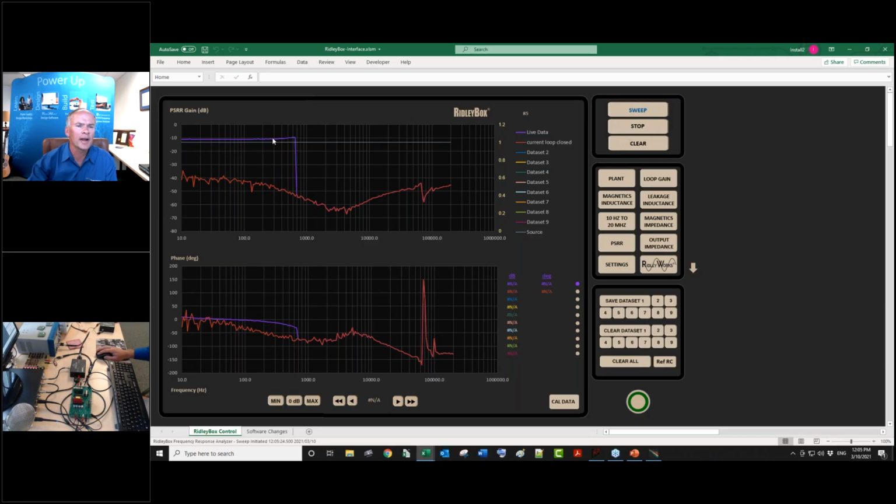Okay, so now you see it looking like an LC filter. There you go. And then we just get into noise issues out here. There's some sneaky bypass paths that this should be attenuating more, but we're so low on the noise, it's just not able to register it. But look, this is the gain of current mode control. You've gone from minus 10 dB to minus 40 dB just by closing the current loop. Here at the resonant frequency, we've gone down 60 dB almost at that point.